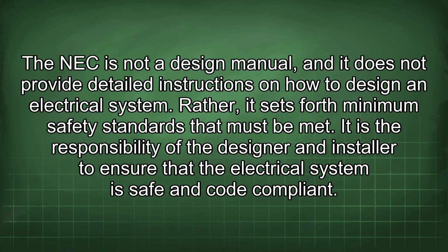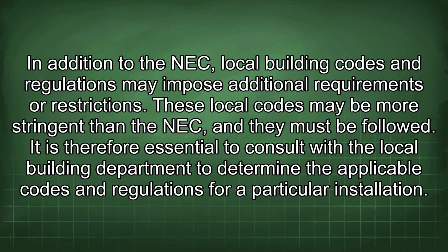The NEC is not a design manual, and it does not provide detailed instructions on how to design an electrical system. Rather, it sets forth minimum safety standards that must be met. It is the responsibility of the designer and installer to ensure that the electrical system is safe and code compliant. In addition to the NEC, local building codes and regulations may impose additional requirements or restrictions. These local codes may be more stringent than the NEC, and they must be followed. It is therefore essential to consult with the local building department to determine the applicable codes and regulations for a particular installation.